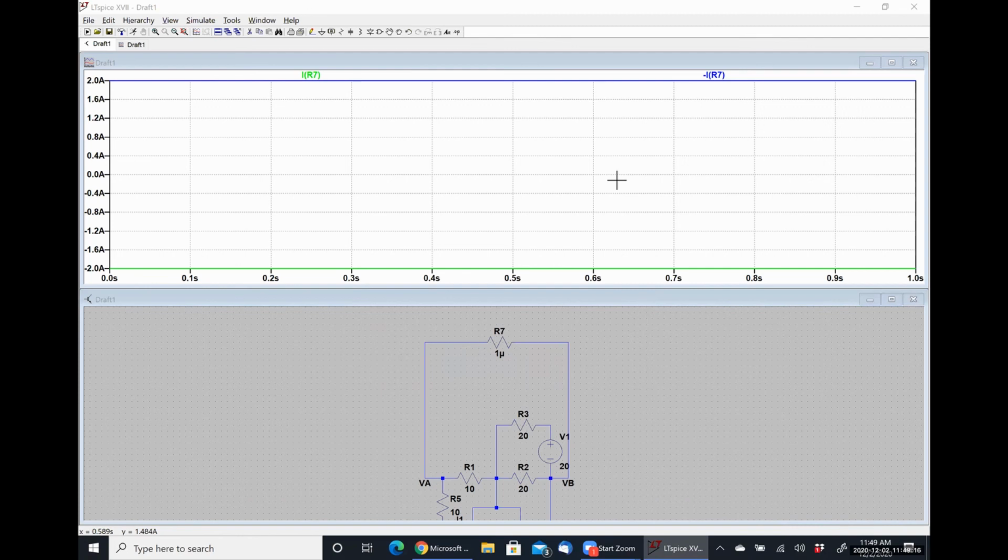For the Thevenin resistance, well, that's easy enough to figure out what it should be. You know what V Thevenin is, you know what I Norton is. Take the ratio of them, that kind of stuff. So you can use LT Spice for literally any and every circuit we're going to analyze in this class. Yes, sir.